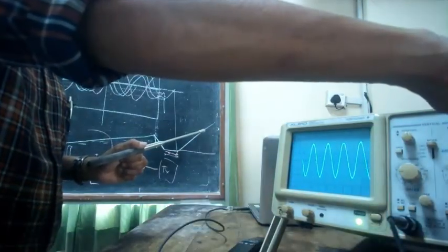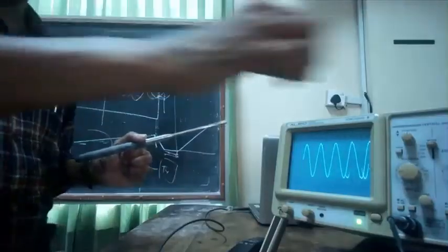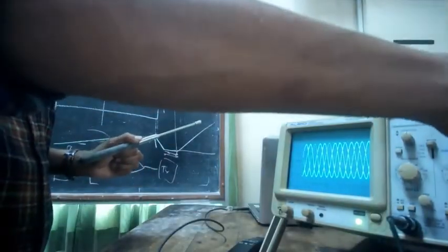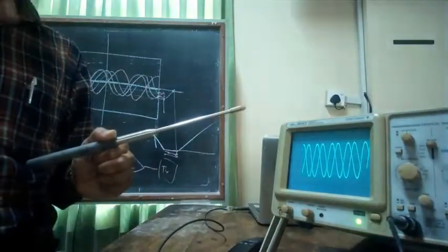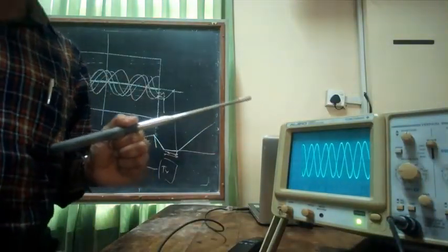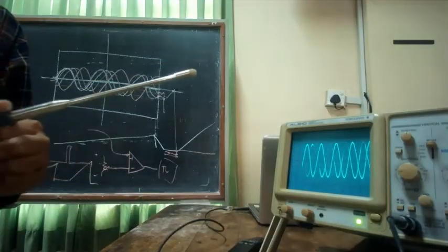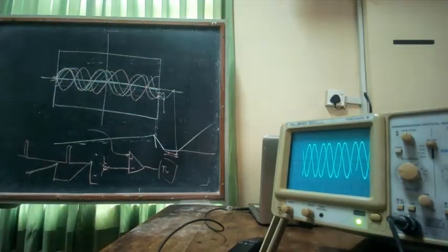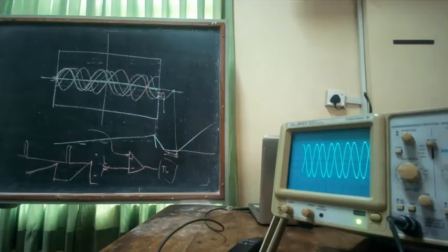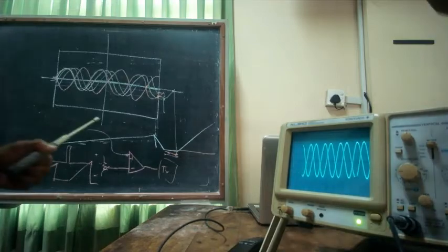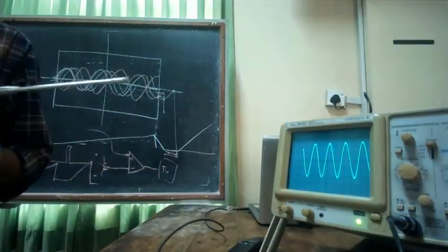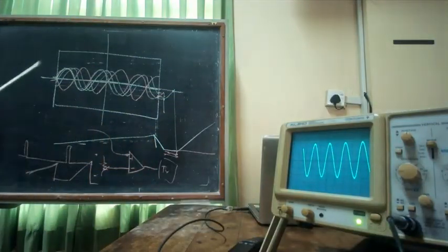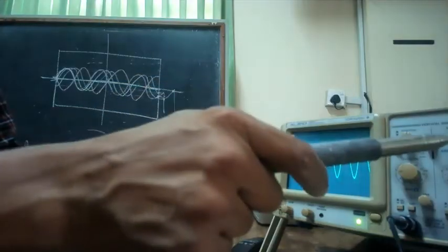Depending on the hold off time, now it's drawing faster. If you increase it, it will be different. So it is how long you wait until the next sweep, without waiting until it reaches that voltage. So that is that. You have these untriggered signals. This is the issue, right? Therefore you need to make sure that you lower the trigger level, or take the trigger level to that signal level. Okay, right.